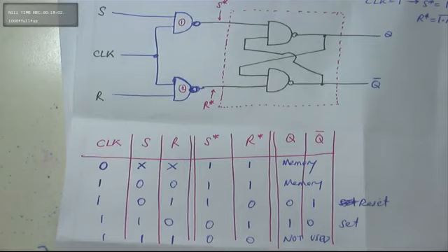All right, now, what if you want to recall the memory? If you want to find out what's stored there before, what are you going to use? Clock should be 1, and our S and R should be 0, 0. Or you could just make clock 0. Whatever is inside will show up. Okay? And of course, there's one line which we don't use. We don't use the invalid line. We design our system in such a way that those 2 bits never appear there.